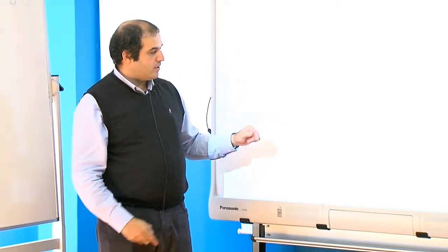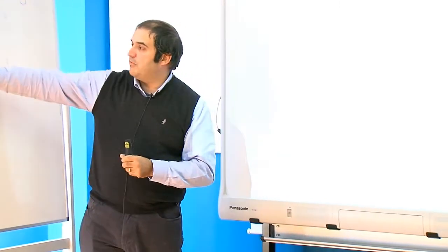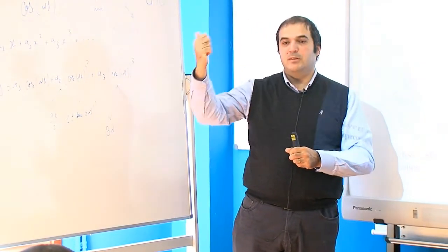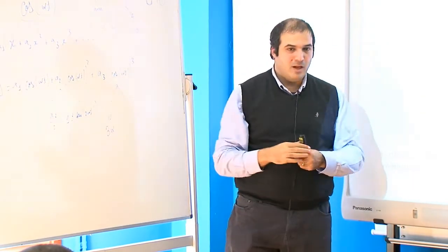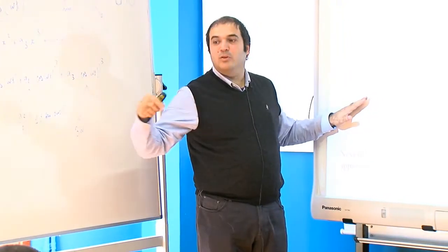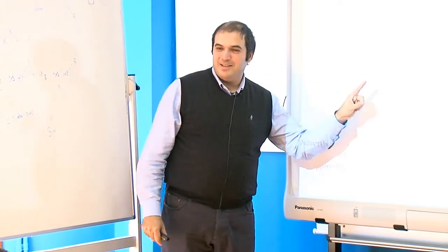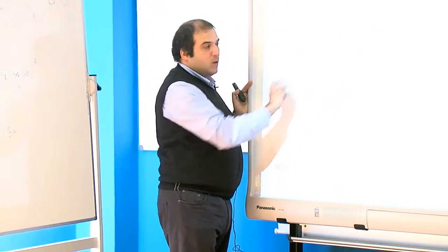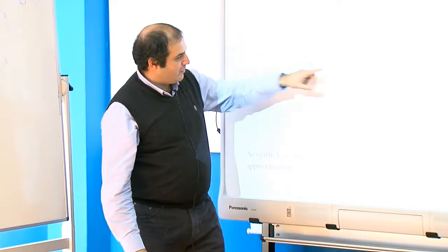And if I look at these components here, what I'm going to see is that these components come from x cubed. So if I have 1 dB at input, this is cubed, so I will have a 3 dB increase at the output in terms of the harmonics, you see? So what I will see is that my intermodulation is going to increase at 3 dB for each 1 dB that I increase at input. So what you'll have is a curve like this, you see? And when it starts to compress, then here I can have different behaviors. I can have this, I can have something like this, I can have strange behaviors, okay?